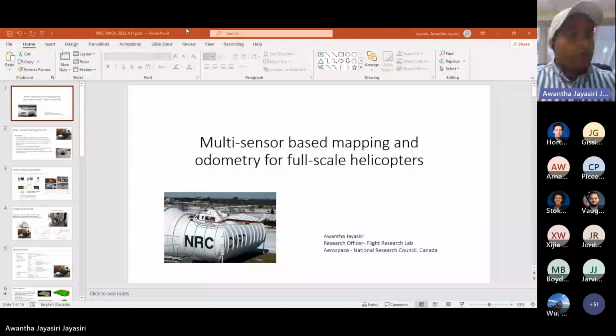The visual and inertial information is fused with the LiDAR scans to improve the accuracy of the mapping and state estimation. This provides a better automated solution for the aircraft, even with the absence of GPS data. The perception solution also includes deep learning-based semantic segmentation, object identification, and landing zone detection as submodules.